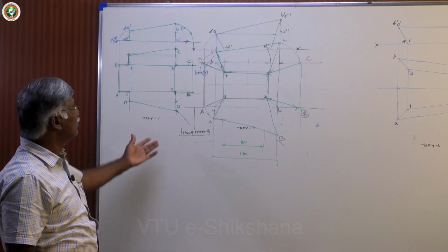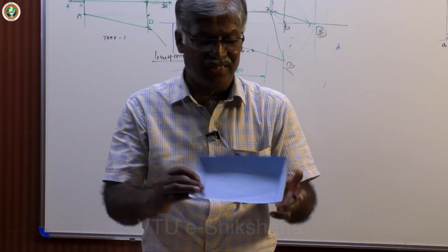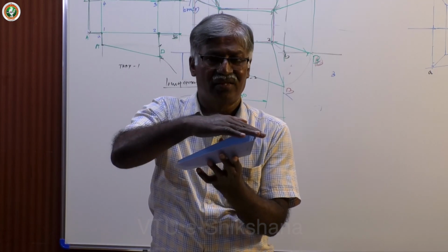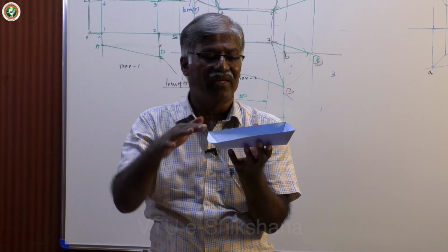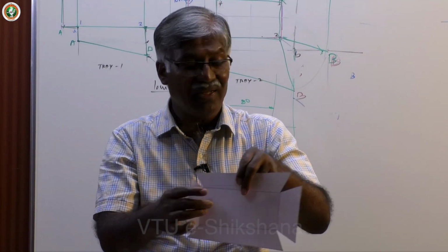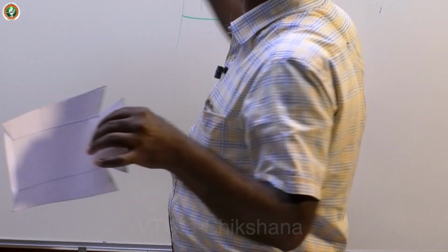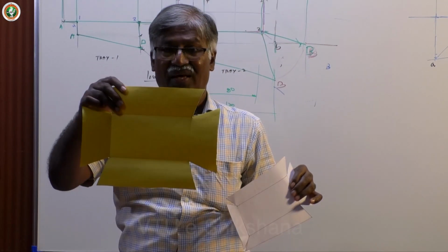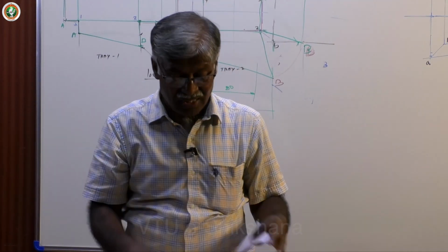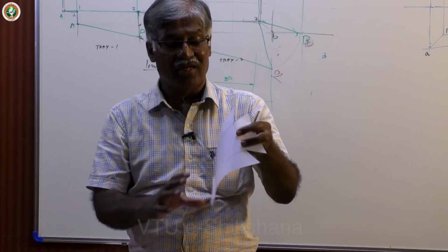Okay. So, tray 1, tray 2. Here different height I have this one. See, the same rectangle is there, and here the height is 20, this is 10. Okay, so you have a slope. So if you cut it open, then you will get this. See, this is smaller and this is bigger. So here the inclination will be there. But unlike the previous one, where we have horizontal and vertical in the top edges also, here we have inclination because of the slope. So here is the model of the inclined tray and the corresponding development.